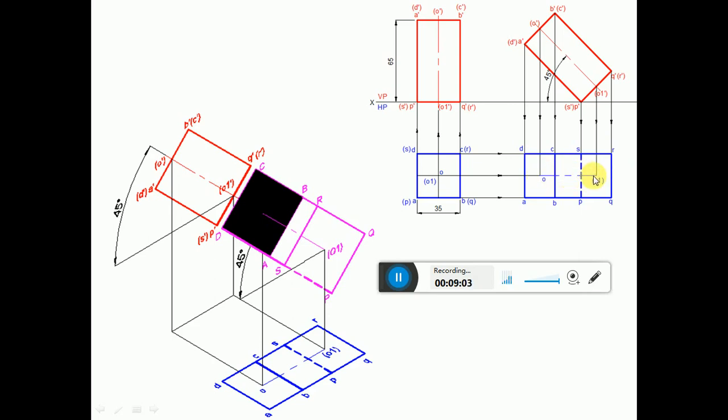Now we are going to apply the condition of visibility. All the exterior edges of the boundaries of the solid are visible. A to Q, Q to R, R to D and D to A are the exterior edges of the boundaries of the solid, so you dark them. Similarly, when you look from the top view, ABCD is near to the observer, so it becomes visible. BC becomes visible, you dark them. Since ABCD is completely visible, naturally O is visible.